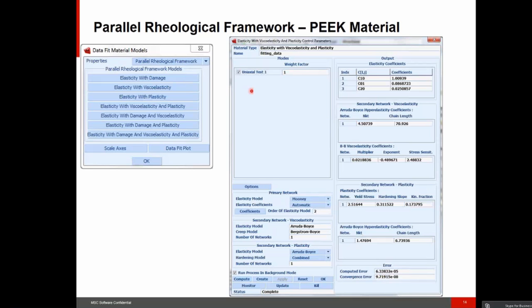So it's very easy to do. You would specify your table. In this case, it's a ragged table. We'd have time as the independent variable, strain and stress as the dependent data, and we would have selected all the different models. That's here a Mooney-Rivlin model. Only a single term Boyce, a single term plasticity model, and it would have calculated these coefficients. And the more series you would have had, the more coefficients you would have effectively.